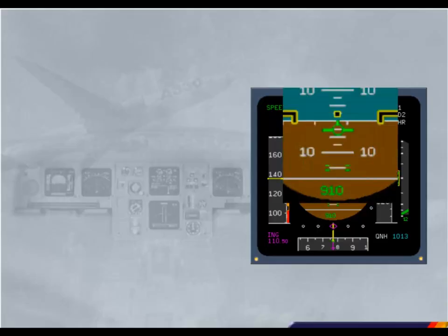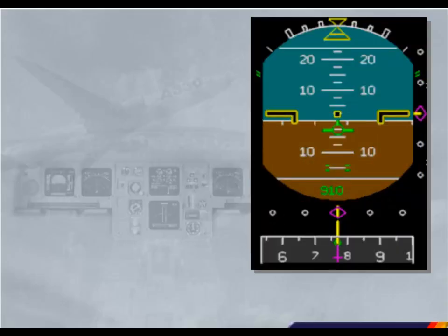The flight path vector can be displayed on the PFD to show you what the aircraft is doing in relation to the outside world. It is an indication of the aircraft flight path. It is not a director. The green symbol, sometimes called the bird, represents the aircraft. The attitude indicator represents the outside world. Let's look at the FPV in a bit more detail.